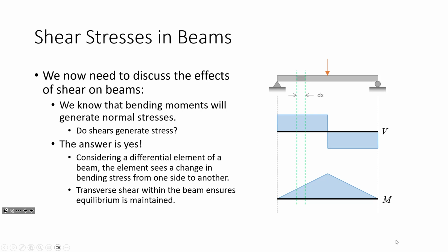Okay. Now, what we're doing for today is I want to make sure that you all understand the effects that shears generate on flexural elements. I have here on the right a simply supported beam, and I put a concentrated load in the middle. I think by now you recognize that the shear diagram has this sort of stair-step feature to it, and then the moment diagram is linear and peaks at the top. Hopefully, after having me for CE 312, you all are able to construct that. I don't think there's anything that's all that confusing about that, right?